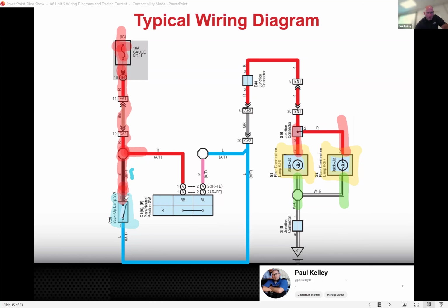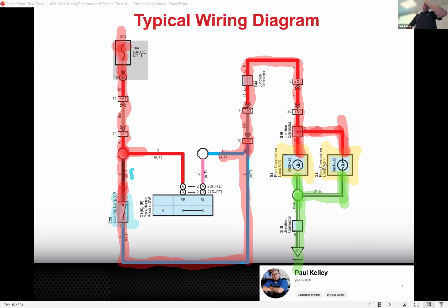Okay, cool. And then when we close the switch, we should have voltage coming all the way down, all the way up, and it would go that way, but we don't care. CA2, AE3, a junction, EN1, SN1, a junction to the bulb, and to the bulb. At that point, the load should consume the voltage, leaving about 0 left over, and so this should all be ground all the way to the chassis, both sides. That would be the correctly traced backup lamp circuit.